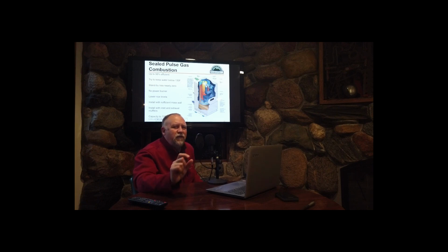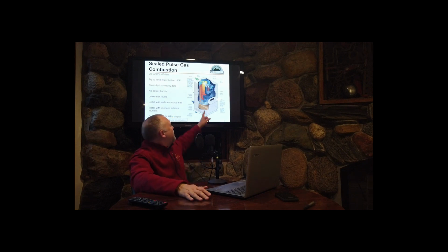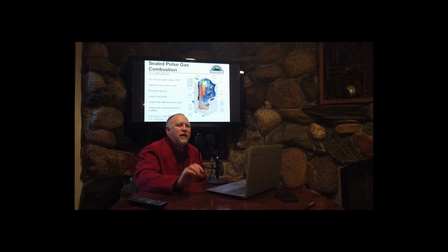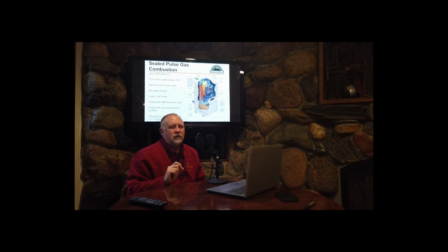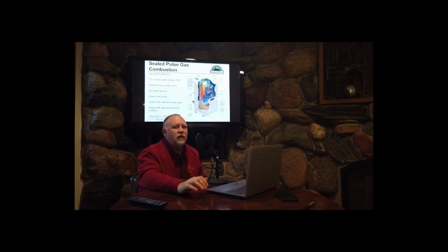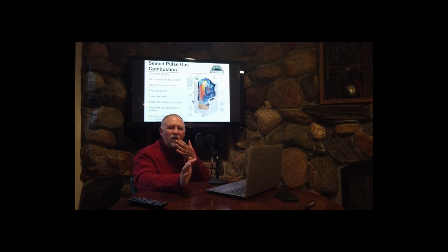So how do I maximize efficiency in a boiler? One, pick materials that are good conductors, like copper, or maybe stainless steel. Maybe I increase the surface area. In other words, I have a lot of these coils in here, right? Maybe I make the wall of those coils as thin as possible. Notice that last one. That increases the heat transfer, but thinner and thinner coil walls increases the chance of failure. So there's our trade-off. I'm trading off life expectancy for performance.